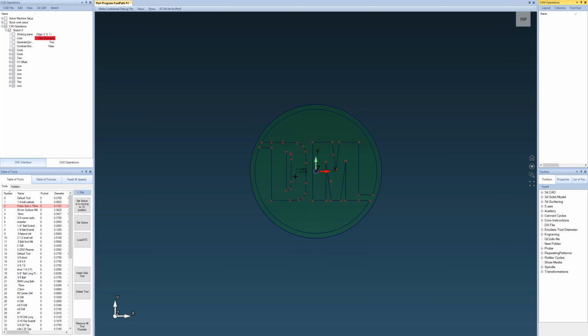So this is a lot easier if you know where the plane is that you want to move the sketch to, but that's not usually the case when you're on a machine. You just have a part, typically a cylinder head or something like that, and you want to do a little bit of 3+2 milling on one surface, and that's not clearly defined. So I'm going to show how to do it using the probe of the machine to get a 3-point plane and then create a toolpath on that sketch.